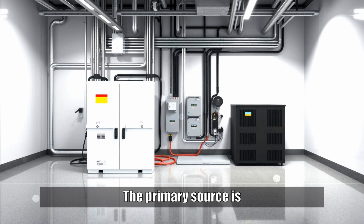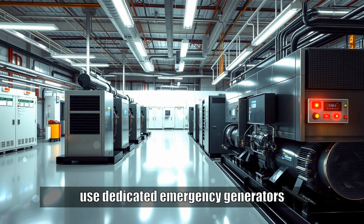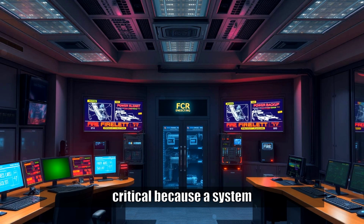The primary source is typically the building's main electrical power, but every compliant system must also have a reliable secondary or backup power source, usually a sealed lead-acid battery or an uninterruptible power supply, UPS, to keep the system operational for a minimum of 24 hours of standby and 5 minutes of alarm time in the event of a power outage. Larger facilities may also use dedicated emergency generators. Maintaining continuous power is critical because a system failure during a fire event can lead to catastrophic consequences, both in terms of property loss and human life.